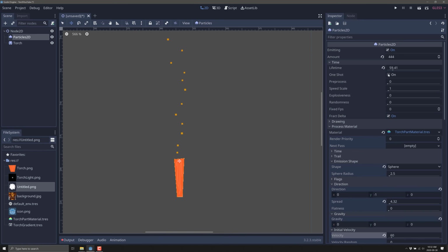Of course, if you want to burst your particles, you could set it as a one-shot. And then you come up here and you can basically do a restart. And that will spit them all out accordingly. So the duration, or the life cycle, of your particles will be controlled up here. Basically, the longer that value is, the more particles will be created over time. If you want to have even more particles, easily just keep jacking that up. You'll end up with more precision as a result.